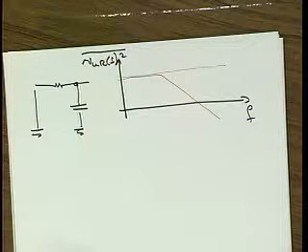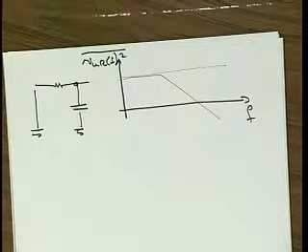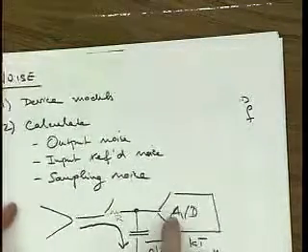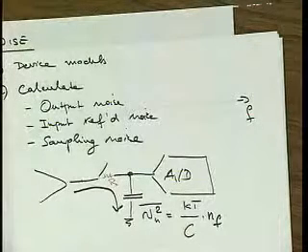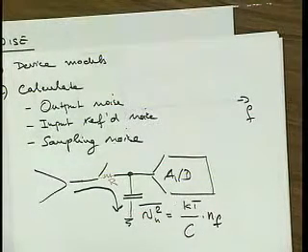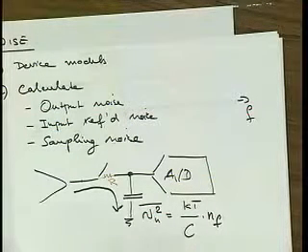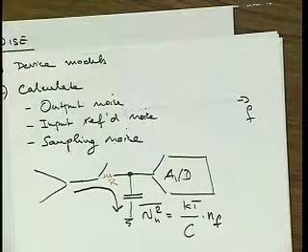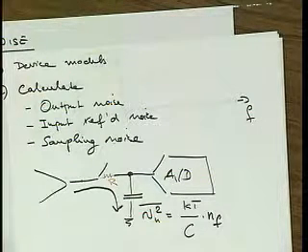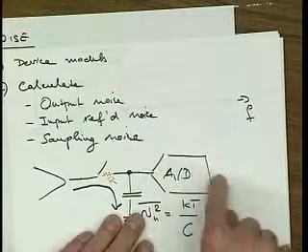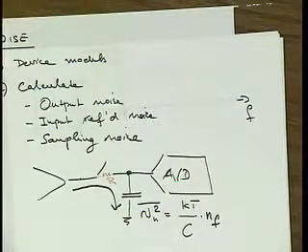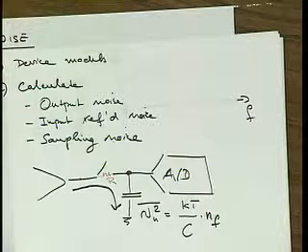Now, question. The A to D converter is going to convert the signal and also the noise. Let's for a moment make the signal 0. We'll use superposition so we can deal with one thing at a time. So we'll talk only about noise. The A to D converter now is going to convert these random noise samples. What is the spectrum of those going to be? Let's say this A to D converter is hooked up to MATLAB and you can type FFT and it gives you a spectrum. What is that going to be like?